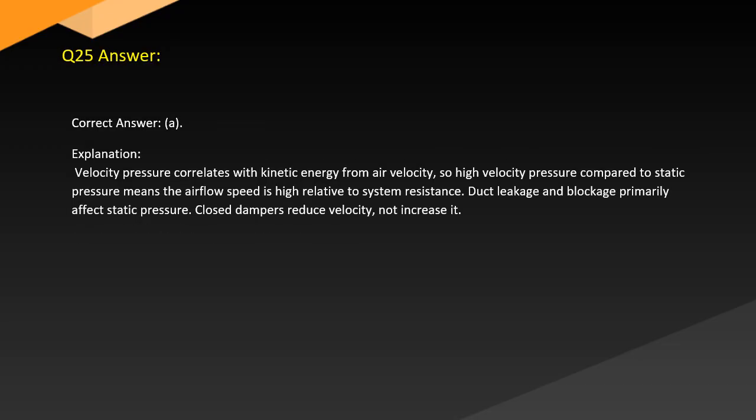Answer. Correct answer, A. Explanation. Velocity pressure correlates with kinetic energy from air velocity, so high velocity pressure compared to static pressure means the airflow speed is high relative to system resistance. Duct leakage and blockage primarily affect static pressure. Closed dampers reduce velocity, not increase it.